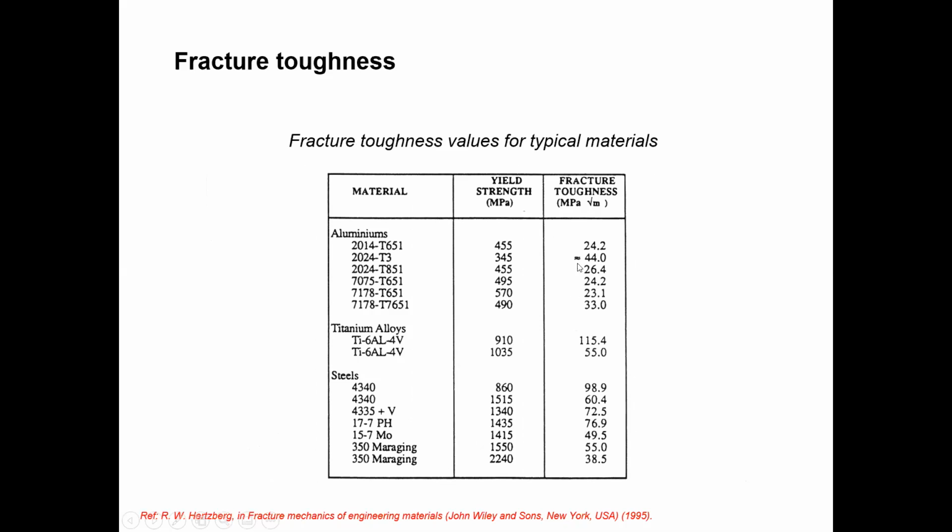So normally in the questions, if they provide this kind of table in the annex or somewhere, and they provide in the equations what the material is, sometimes they will not mention that you need to find the fracture toughness. So you need to use that particular table and find the KIC value. And you can use that in the equation to find the critical crack length or maximum stress value or something like that. It depends on the question.